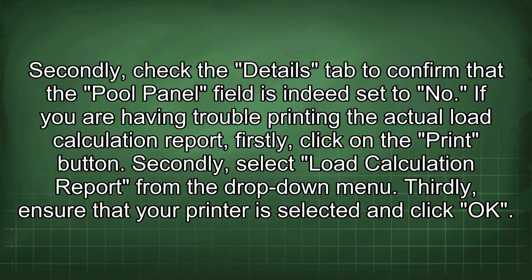If you are having trouble printing the actual load calculation report, firstly, click on the Print button. Secondly, select Load Calculation Report from the drop-down menu. Thirdly, ensure that your printer is selected and click OK.